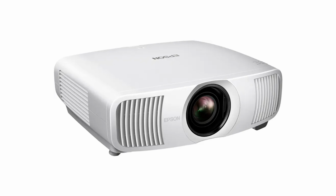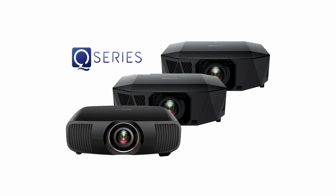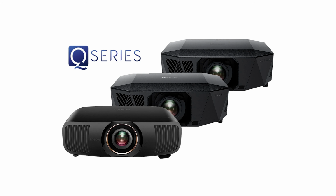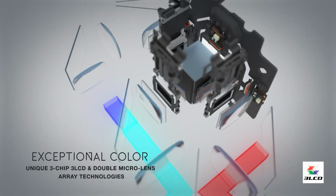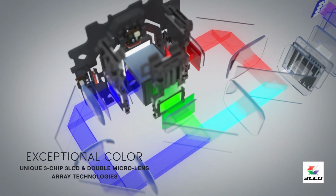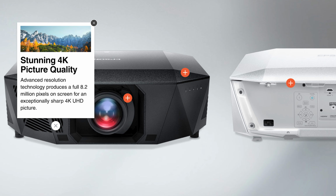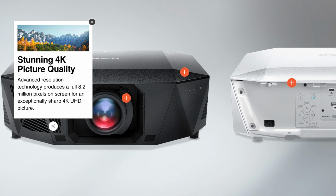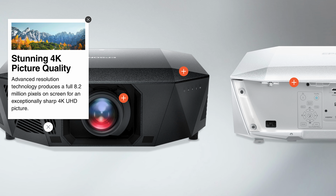Select Epson projectors such as the LS11000 and LS12000, as well as the Q-series projectors introduced in 2024, use quad pixel shifting. Instead of only shifting the pixels diagonally, they are shifted horizontally and vertically back and forth at the rate of 240 Hz. This process results in the display of 8.3 million pixels, which is a more accurate representation of a 4K UHD resolution.